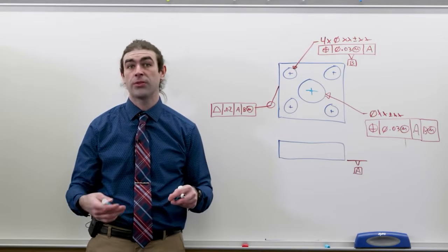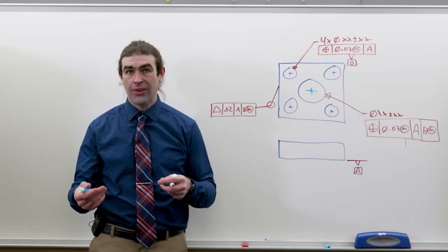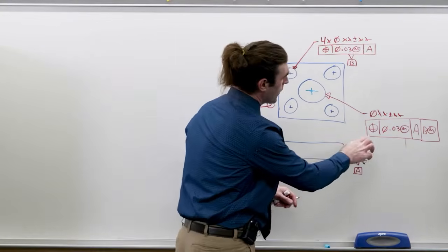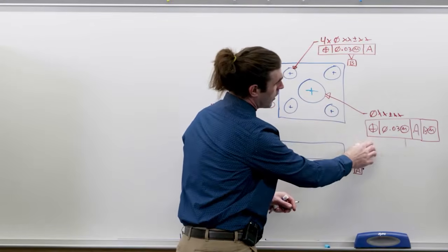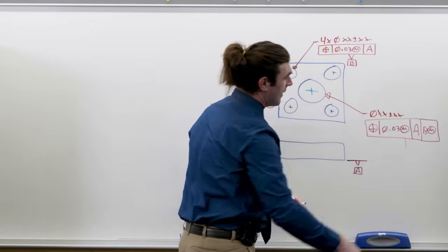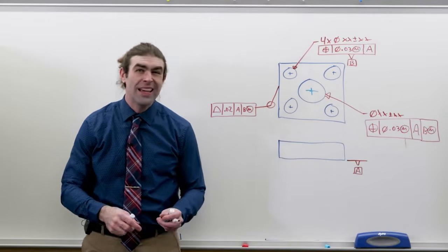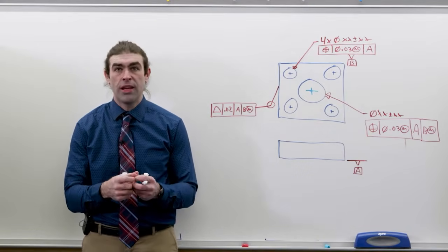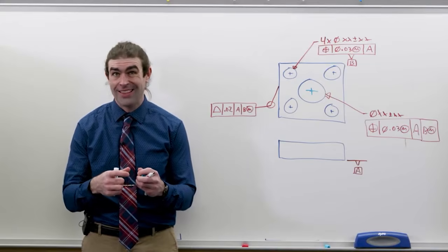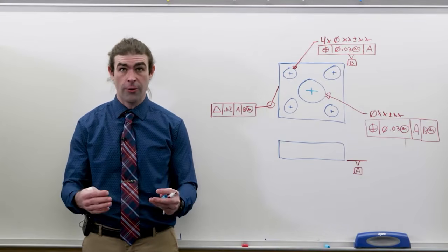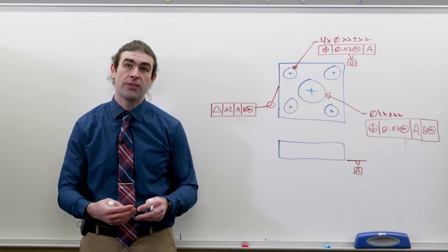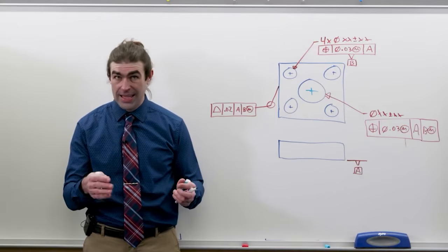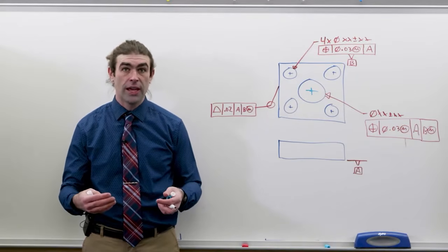Again, on a CMM, this is super easy. On a plate, you basically have to have this set at MMC. The reason, when we look at this center hole, right, we're going to position it to datum A and that pattern of holes. If you called that out at RFS, you would have to have 4 pins that expand at the exact same time, that are perfectly located, so at least gauge maker's tolerances. They all expand to capture the part until it stops wiggling. That can be done, and they do make fixtures and gauges for that.